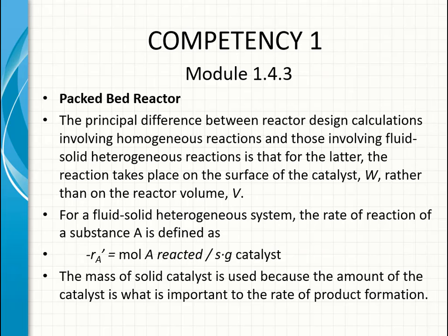Packed bed reactor. The principal difference between reactor design calculations involving homogeneous reactions and those involving fluid-solid heterogeneous reactions is that for the latter, the reaction takes place on the surface of the catalyst W rather than on the reactor volume V. For a fluid-solid heterogeneous system, the rate of reaction of a substance A is defined as minus RA prime, equal to the moles of A reacted divided by the time times the weight of the catalyst.